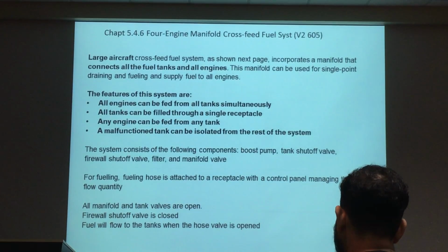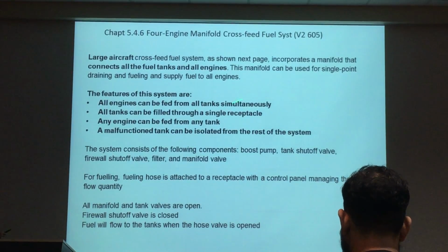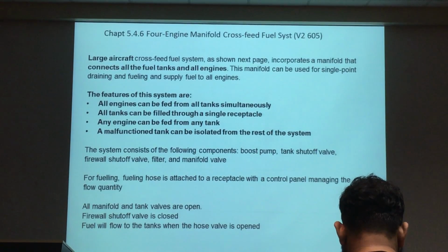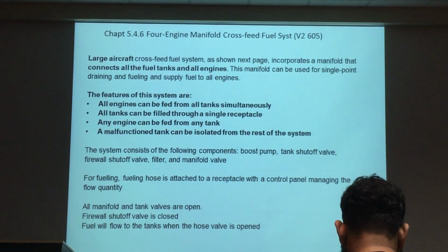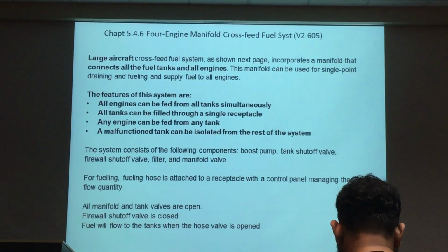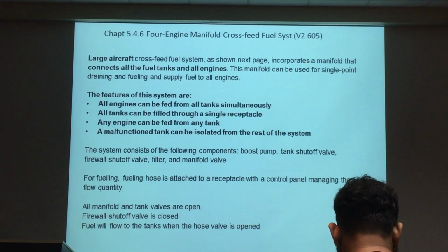Okay? When you design the aircraft fuel system, you must follow the basic features. Okay, this feature here. It's a design rule. When you design this system, you must follow this rule. Okay, all engines can be fed from all tanks simultaneously. Okay, maybe tank to tank feed. This is a basic requirement. Left tank feeds left engine, right tank feeds right engine. This is a basic requirement. Okay, all tanks can be filled through a single receptacle. When you do refueling, you only refill from one point, but you can fill all tanks. You must have this design.